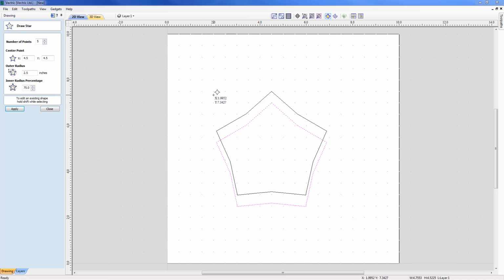Now moving on from just specifying the radius or diameter of the star, we can start to add in the number of points. As you can see here in the form, it's currently set at 5. So as I start to grow that now, you can clearly see there are 5 points projected on the screen. Now I can add in the number of points by once again using the transform shortcuts. So I'm going to add in 8p, which is going to specify my number of points, followed by the diameter or the radius. In this case, I'm going to go 4D, and we have a 8-pointed star, which is diameter 4.